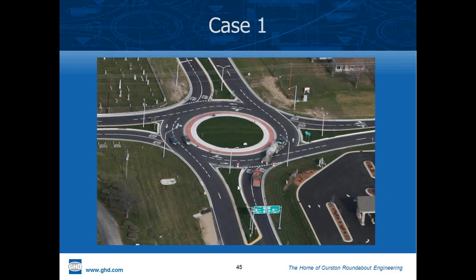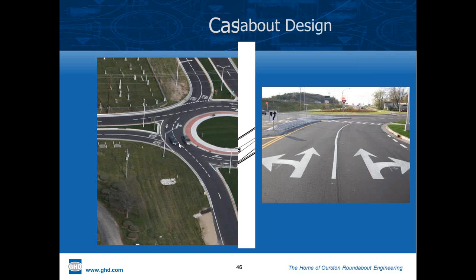So in the discussion of cases, this is a rural roundabout with flared entries, and so 2 lanes drop to 1 in the exits, single lane expands out to 2 in the entries, and it's a case 1. So there's no lane discipline for the largest truck. They'll enter and they'll circulate over tracking lanes. And you can see side-by-side passage of cars in 2-lane roundabouts.